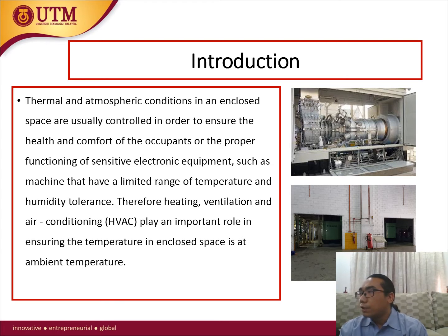The concept of a design cooling load derives from the need to determine an HVAC system size that, under extreme conditions, will provide some specified condition within a space. The space served by an HVAC system is commonly referred to as a thermal zone or just a zone. Usually, the indoor boundary condition associated with a cooling load calculation is a constant interior dry bulb temperature, but it could be a more complex function such as thermal comfort conditions.